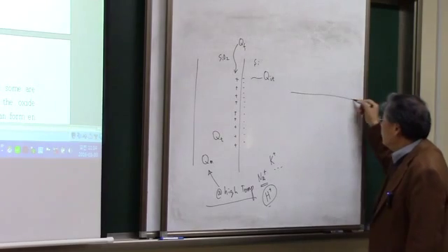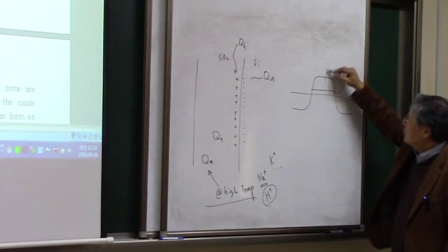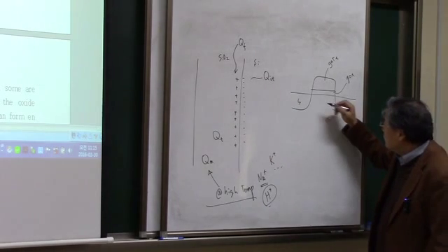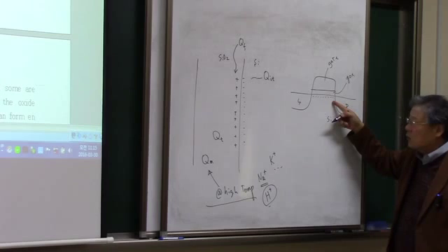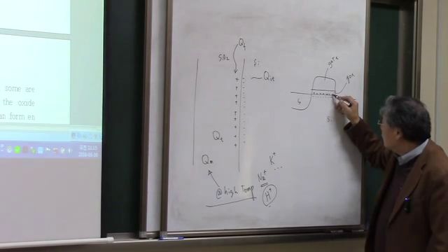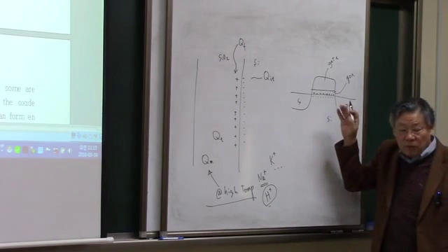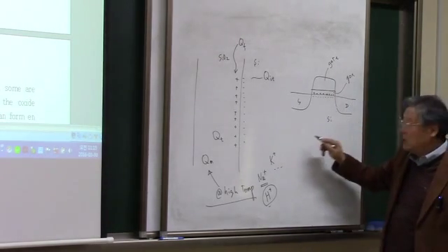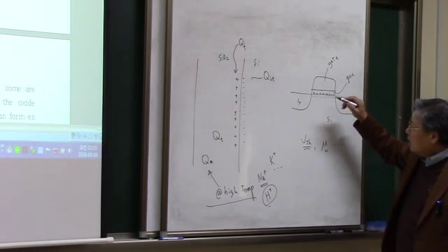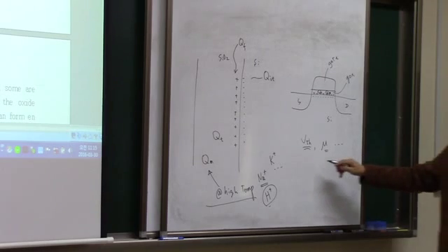And when you think of the transistors, something like this is the gate oxide, okay? And this is the gate, and the source and drain, and this is the silicon. Now, according to this definition, at the channel on the silicon side we are going to have interface trap charges and the corresponding fixed charges in the oxide. We're going to have charges like this. And these charges, of course, affect the electrical properties of the transistor, especially the threshold voltages, mobilities, and so forth. Okay, and again, the trap charges here and the mobile charges here also affect these properties as well.